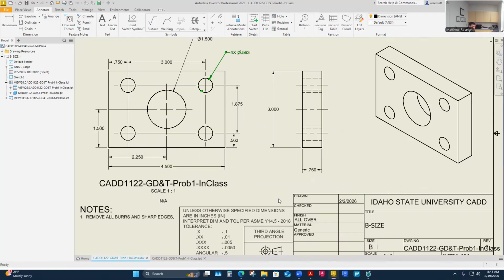Like really, yeah, we would think we're done, but if we want to control this hole pattern way more carefully, let's do this. We can control it with the existing tolerances here. And so let's take a look at what that looks like. And what that looks like is there's an existing tolerance because I have a tolerance block on my drawing. And if I didn't have a tolerance block on my drawing, I should throw that drawing away and be like, I can't even build to that, right?